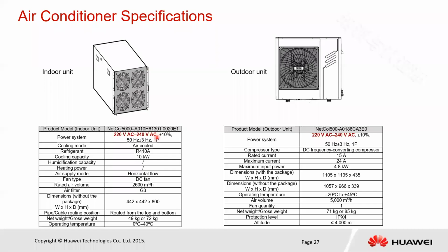Now the cooling subsystem, as I mentioned, has an indoor and an outdoor unit. The indoor unit is very much modular, rack-based in design. It can operate at different levels and ratings. Depending upon the workload, it can increase or decrease the fan speed and make the cooling arrangements within the cold aisle. The outdoor unit can also be monitored by the sensing cable. There is a signal cable going to the outdoor unit too, so we can see whether the fan is working or not working. All these things can be monitored in the same monitoring subsystem.